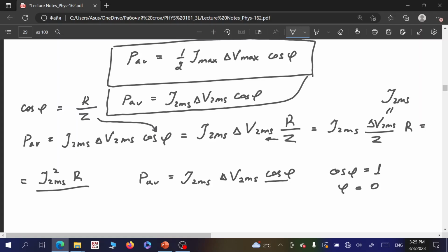They locally attach huge capacitors with variable capacitance, in order to increase capacitance when more consumers are attached to the electric grid. That helps to compensate the excessive inductive reactance of consumers and get the cosine phi coefficient closer to unity.